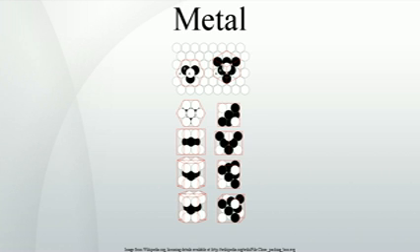Mechanical properties of metals include ductility, that is their capacity for plastic deformation. Reversible elastic deformation in metals can be described by Hooke's law for restoring forces, where the stress is linearly proportional to the strain. Forces larger than the elastic limit, or heat, may cause a permanent, irreversible deformation of the object, known as plastic deformation or plasticity.